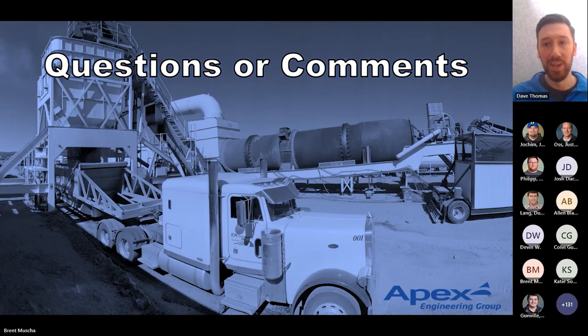So yeah, generally the first thing that people do when they get on the project for the first time is they'll take the app and they'll go stand next to a known control point or a known survey stake. And in really good situations, again, good weather with good hardware, we can be down to within a foot of what that survey stake says. Generally speaking, though, my recommendation would be to, when you're out on the project for the first time in the day, pull open the app, try to find a known location, and that will give you a general relevance of how accurate the app is. We say, again, between 5 to 7 feet, which is close enough for most of the inspection work that's happening.